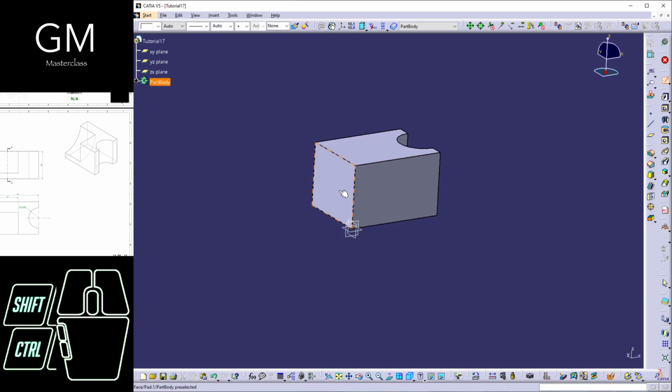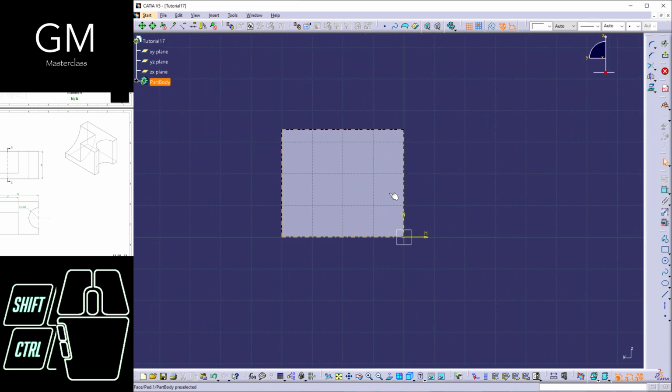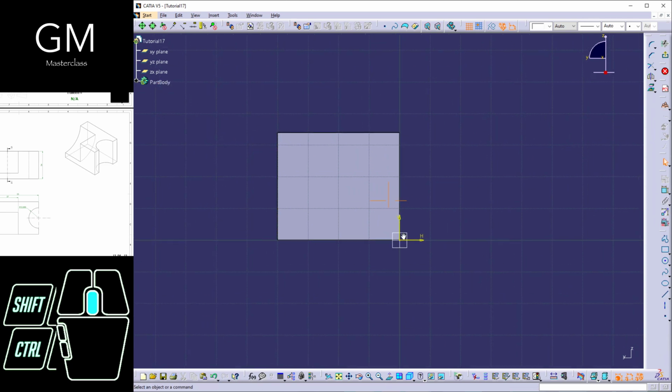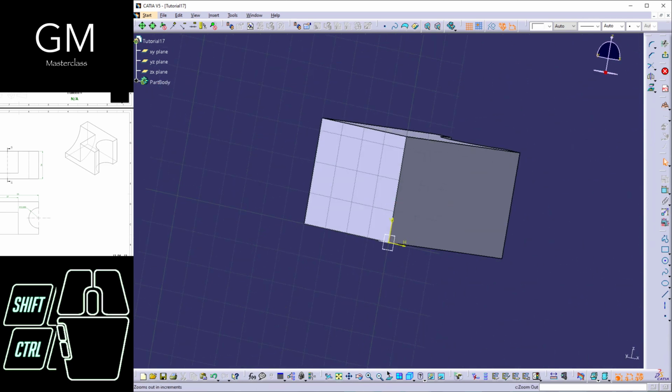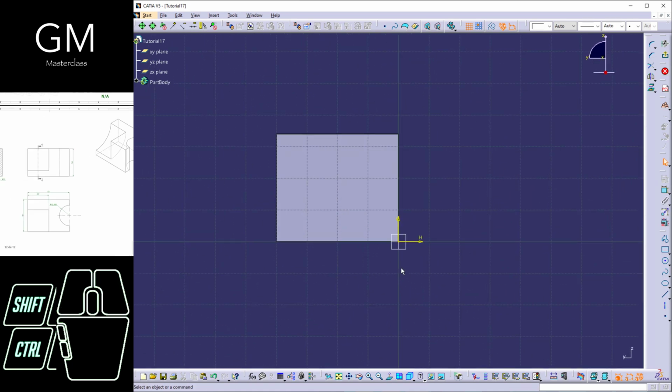So it is created with respect to this face, right? So all I have to do is click on a sketch, select in this case the face, and now we have a perpendicular view with respect to this face, as you can see right here. So all I have to do is create this radius of 27.